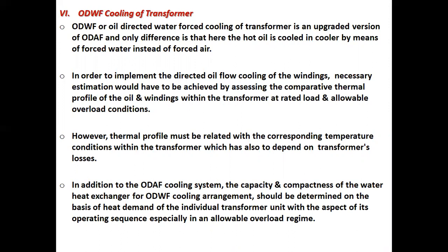In order to implement the directed oil flow cooling of the windings, necessary estimation would have to be achieved by assessing the comparative thermal profile of the oil and windings within the transformer at rated load and allowable overload conditions. However, thermal profile must be related with the corresponding temperature conditions within the transformer, which also depend on the transformer's losses.